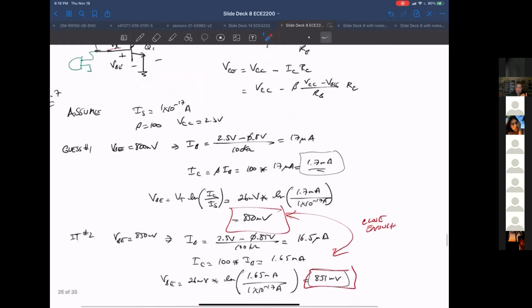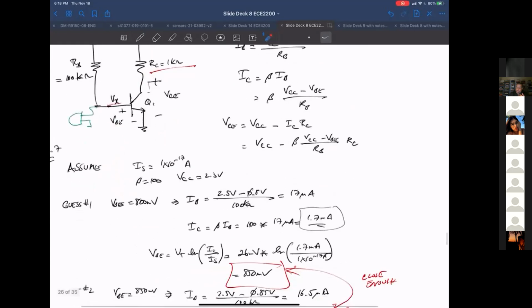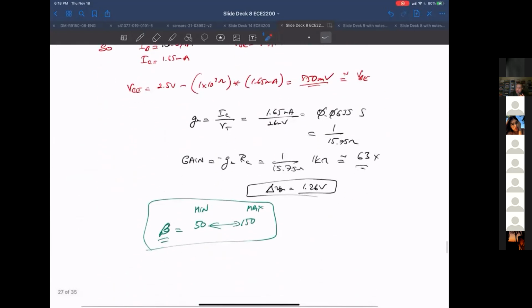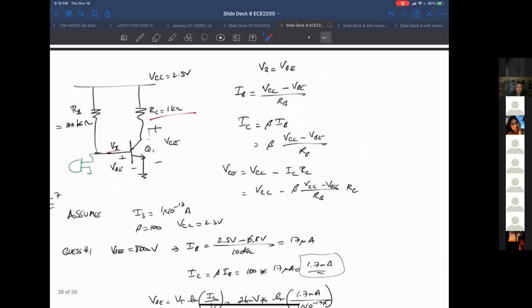Okay, so this transistor is no longer going to be in forward active mode, because its collector voltage dropped below VBE, and significantly below VBE. This approach is very sensitive to this parameter beta, among other parameters, but I'm just harping on this parameter beta of the bipolar transistor.